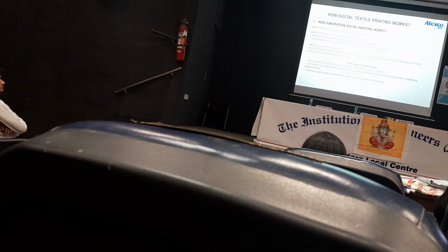by the coated paper, and the third step is fusing and heat transfer. The printed coated paper is then transferred onto the polyester based fabric under extreme heat and pressure using a heat transfer machine. A few things to know here. The coated paper is also known as heat transfer sublimation paper. The process of transferring the print on fabric under extreme heat and pressure is known as the fusing method. The heat transfer machine could be either oil based or electric based.